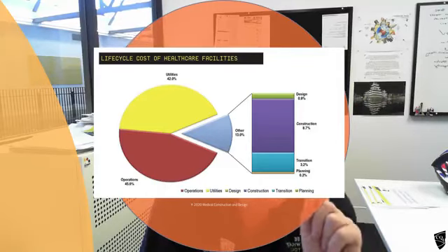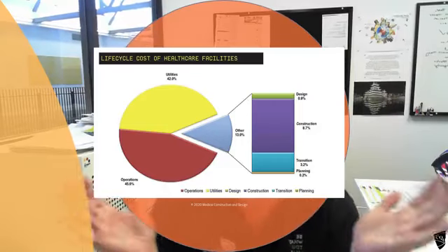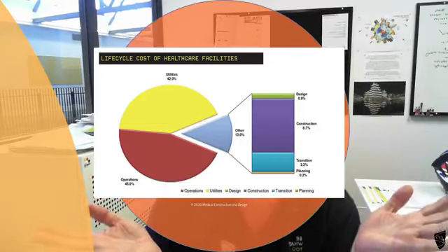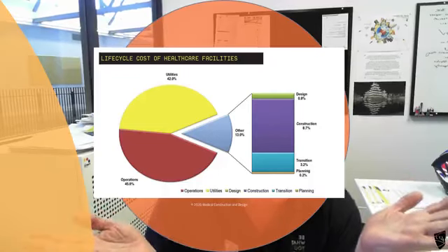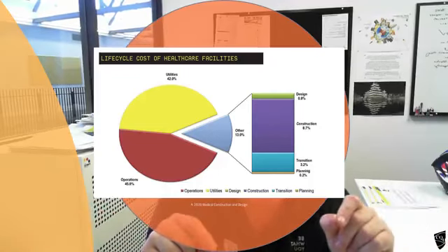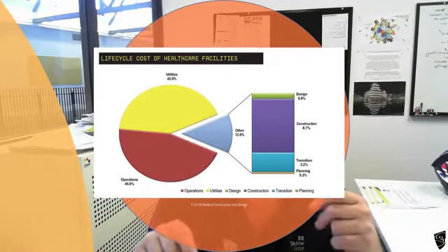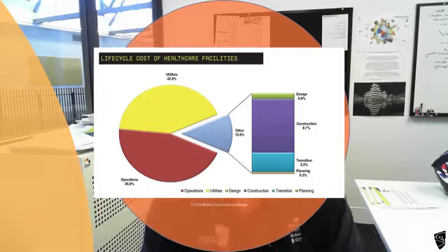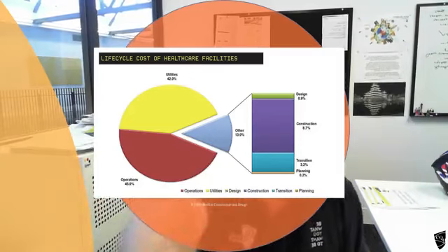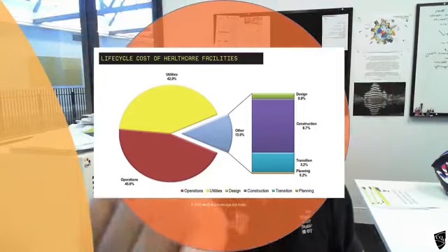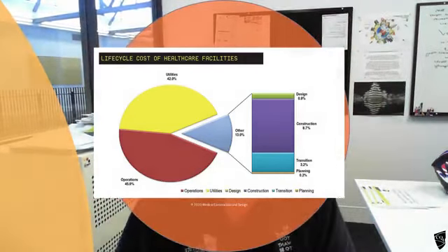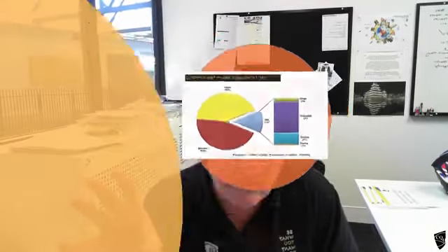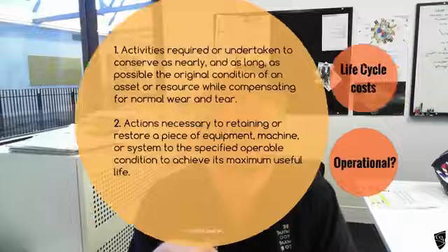So 13% of the cost of the building, and remember, we tender for buildings, and it's normally selected on the basis of the lowest tenderer for the construction, from design to handover. No one seems to really consider the other amounts that we've got up here. So you've got to bear in mind that the running costs of the building far exceed the construction costs.